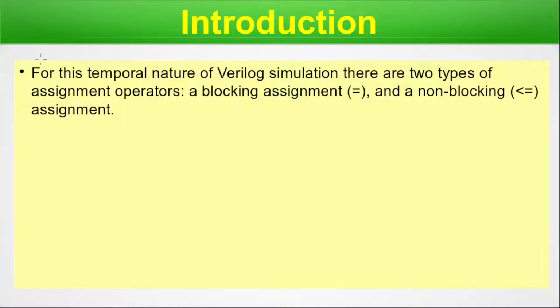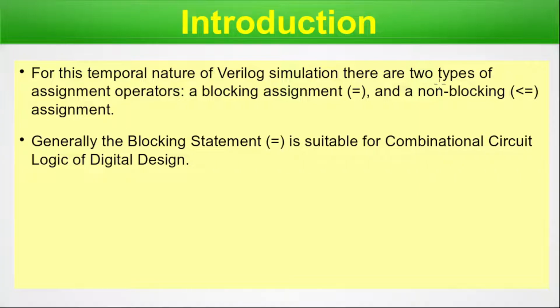Now the temporal behavior is nothing but the timeline-wise response of Verilog. So this is called the temporal nature. To accommodate all that temporal feature or that transient nature of Verilog, we have the blocking and non-blocking assignment. Generally, the blocking assignment is suitable for combinational circuit logic of digital design.